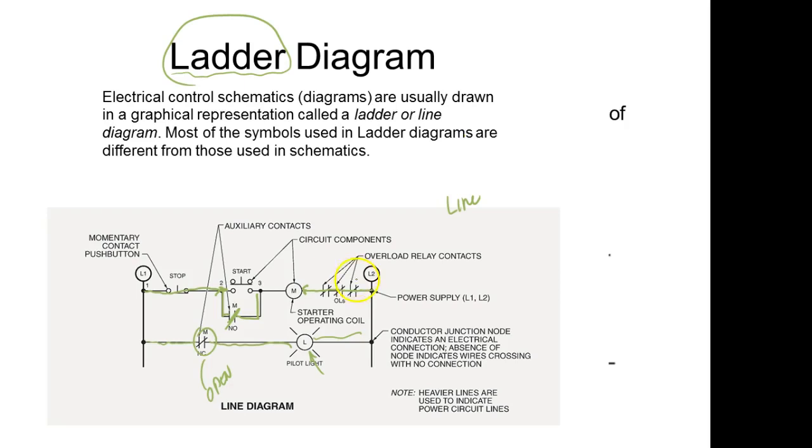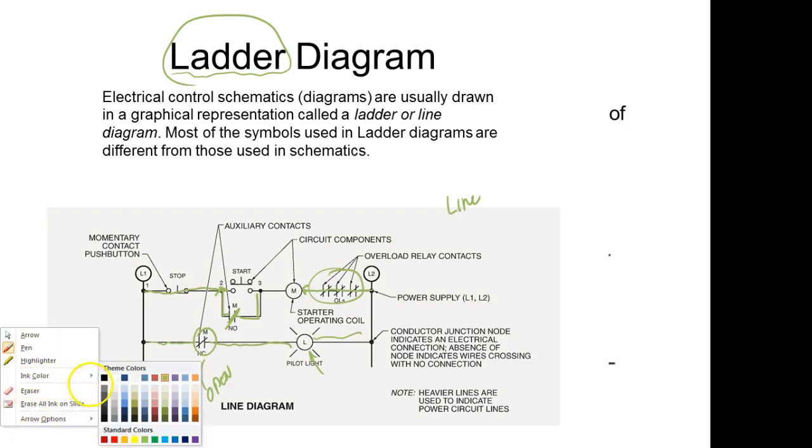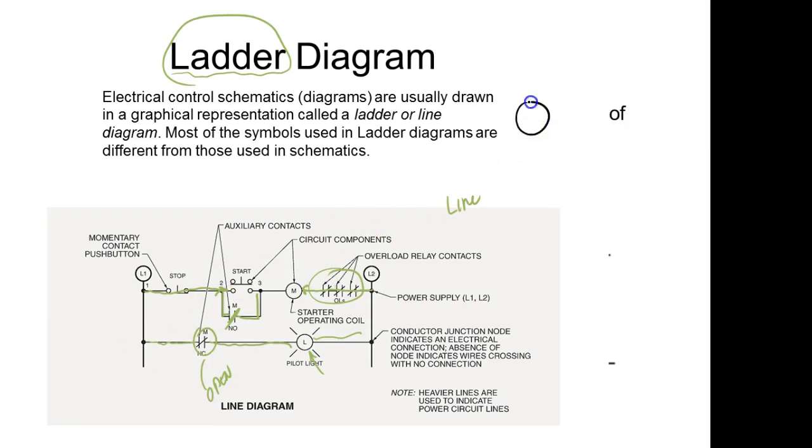Now these are called overloads. In motor controls, this is the symbol of a motor. We have a circle, and we bring the wires in from the top. This would be some type of single phase motor. And if I come in with 3 wires, this would be what we call a 3-phase motor. Those are the 2 types of AC motors we have, and DC motors are a little different. Later on we'll learn a little bit about motors.